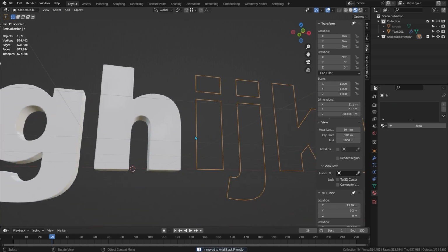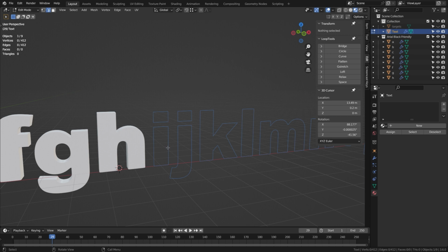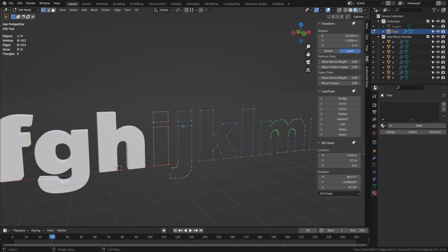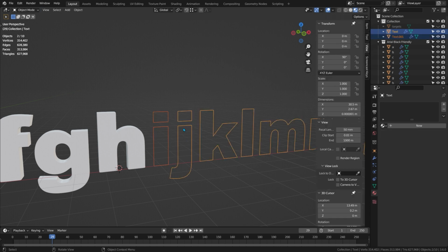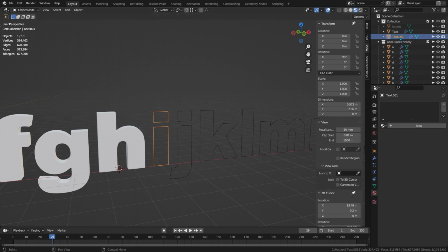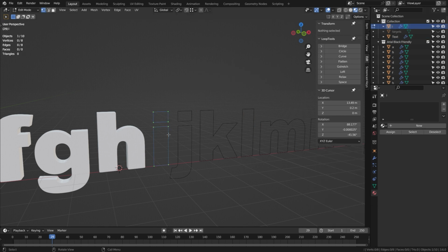Oh yes, it's really easy to do the I. No internal corners or changes of direction. So select the text, tab to edit mode, select both the parts just by alt and clicking on them and separate it into a new object. So P in selection. Tab to object mode, select it and then press F2 and rename it I. And tab to edit mode.